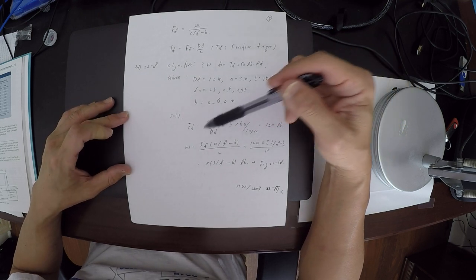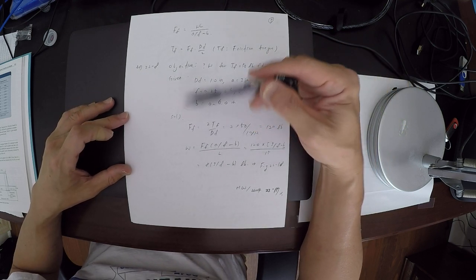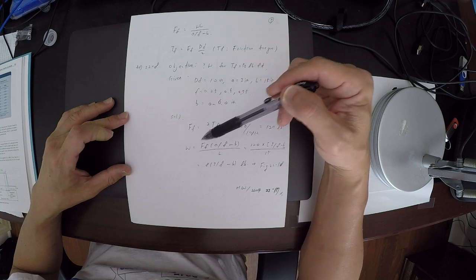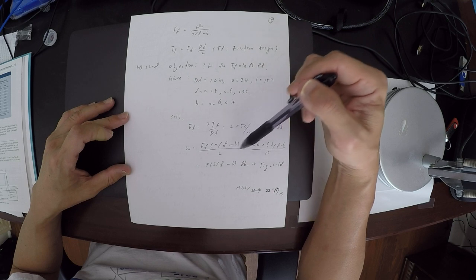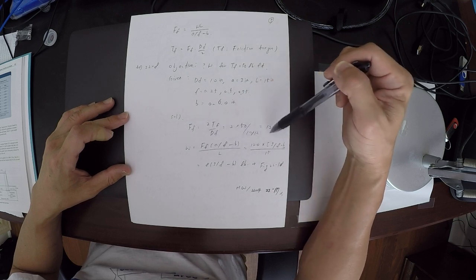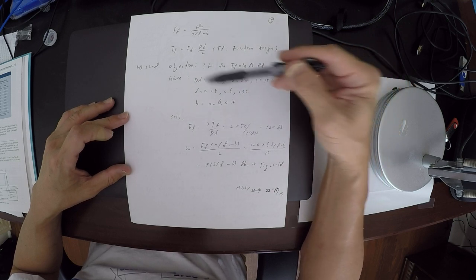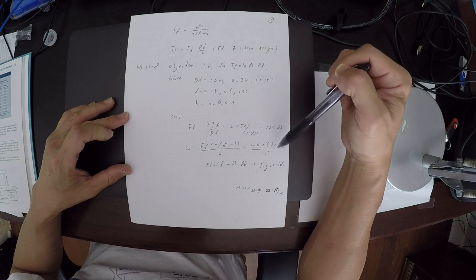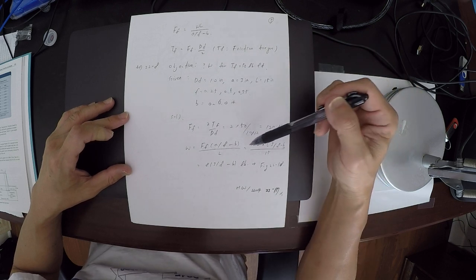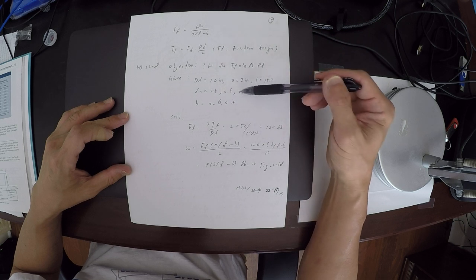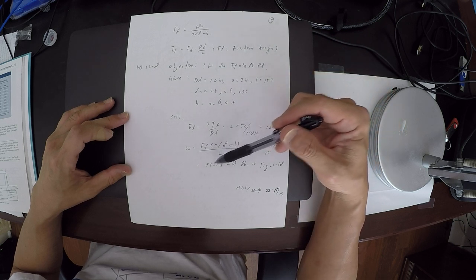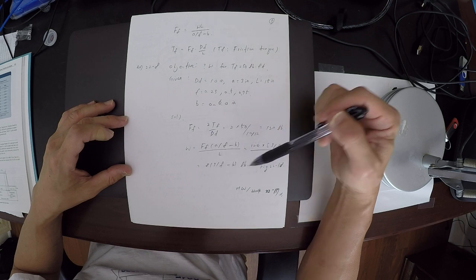And then W, which is coming from the previous equation, the actual force you need to apply, is going to be calculated by the Ff, and then A, B, L, all given geometry, and then the friction f. So as you change your friction for given data points right here, you can actually calculate W that you need to apply, as a function of f.